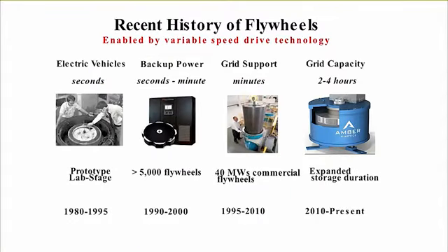Okay, so recent history of flywheels. Let me give some perspective on the meaning of recent. Maybe from the 1980s, and I could explain a little bit about why that's recent. In some sense, flywheel is as old as the wheel. As soon as there was a wheel and it rotated, it stored momentum and it stored energy as well. In terms of modern times, let's say 1980s, I'd say it's with the advent of power electronics and variable speed drives. Go back before that period, energy in, energy out was accessed mechanically.